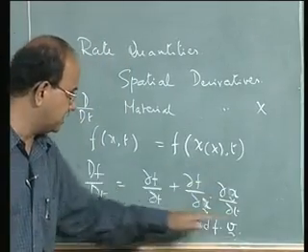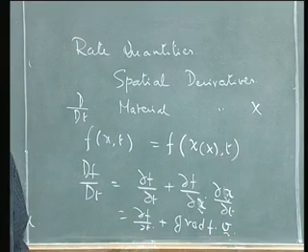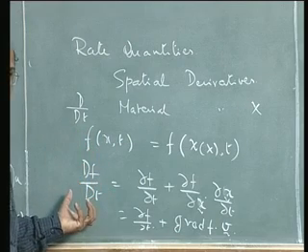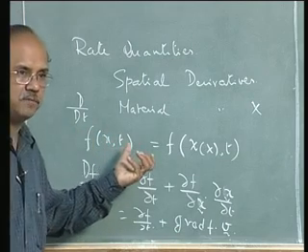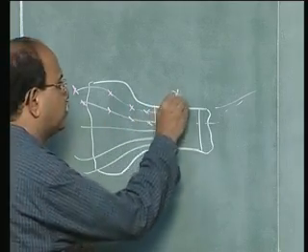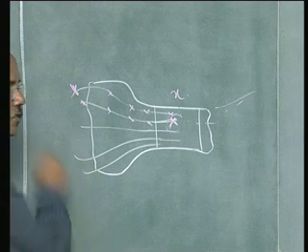The second term is the convective term, and is due to that velocity there. So that's the physical meaning of the difference between a material time derivative and a spatial time derivative. To summarize, for the spatial time derivative we are looking at small x. For the material time derivative, you are looking at capital X.